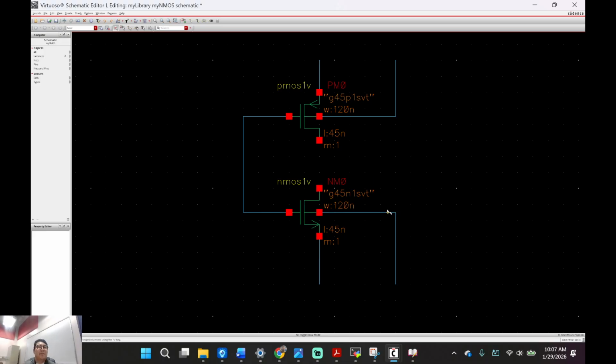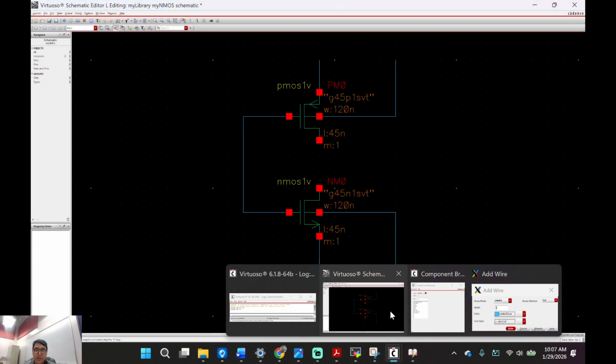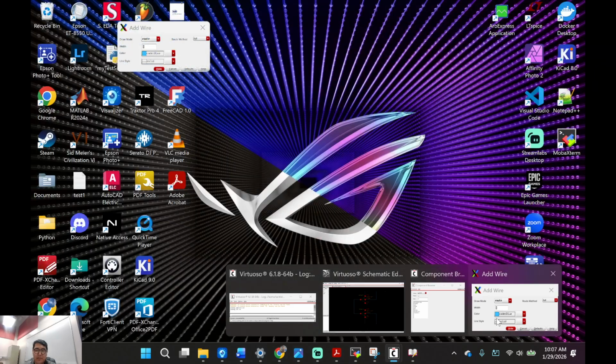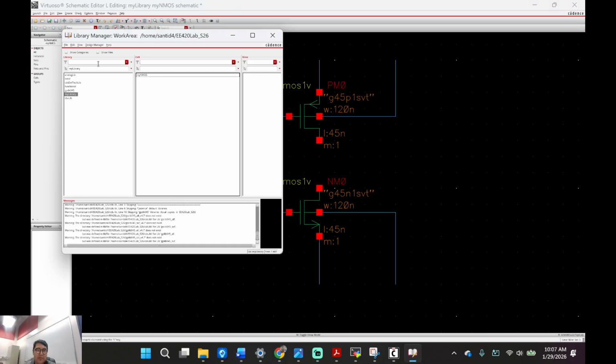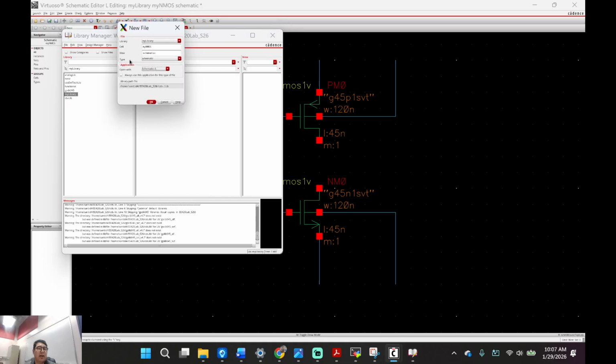Yes? What's up? How do you go from that library tab to that? Do this right here. Yeah. Go to your, let's see, called. So you got to this one right here, right? Yeah. So you go here, you click on this box right here, create file, new, cell view. All right. I don't know why I'm calling this my NMOS.